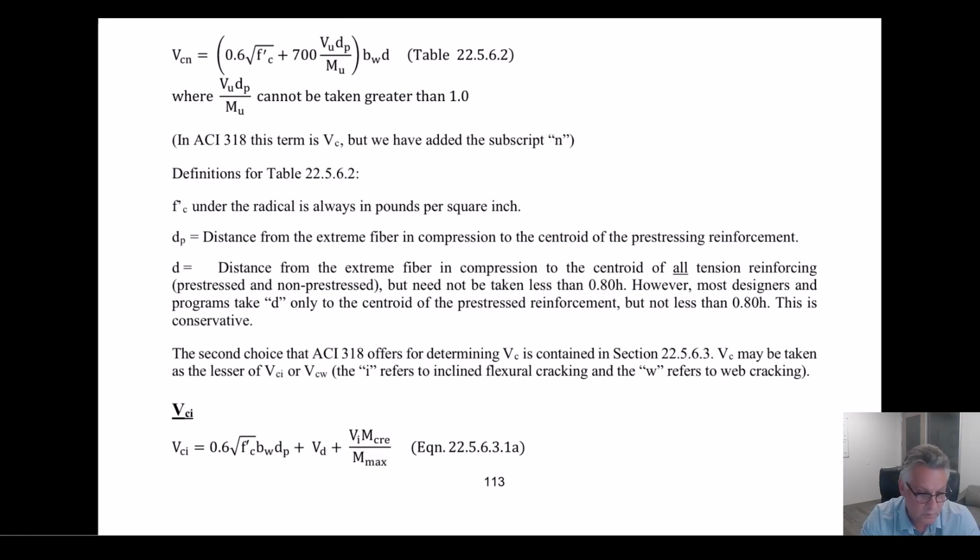So there we go. Another thing to point out, remember, these are capacities. We're just looking for the shear capacity of the concrete only, just the concrete. We're trying to say how strong at this location is the shear in concrete. For some reason, the dead load shear at that location is a term that just simply gets added to what the capacity of the concrete in shear is. I'd love for somebody to explain that to me. How the demand, how the dead, not the live, not any other shear, but the dead load shear is actually additive to what the concrete strength is. The strength and the load, usually you calculate the strength that you have, you check it against the load that you have, and you see if you have more strength than load. But this is actually a component of the strength.